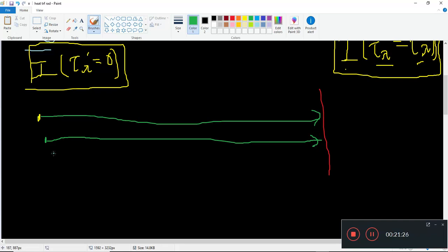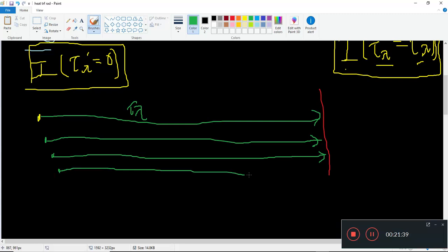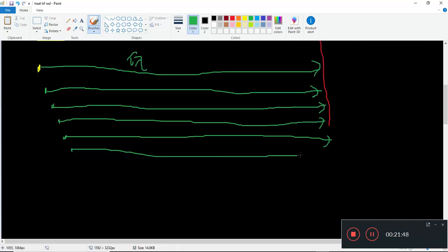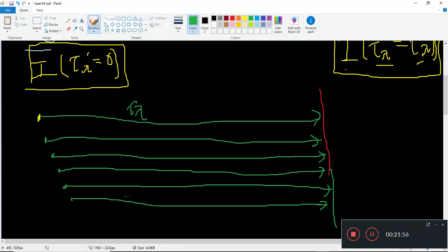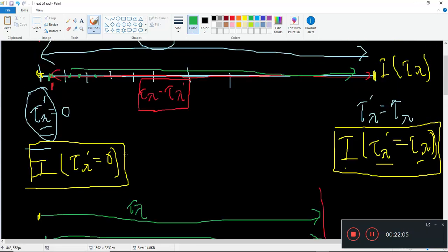Then, as you go through the medium, you have some other radiation sources as well: the in-scattering and the, what? Emission term, right? So this is going through tau lambda. Along the way, there will be different source terms, all traveling towards the end. This is along the same line here; I'm just drawing it in different directions. And as you can see, the closer the source is to the finish line, so to speak, the shorter the optical distance the radiation has to travel through.